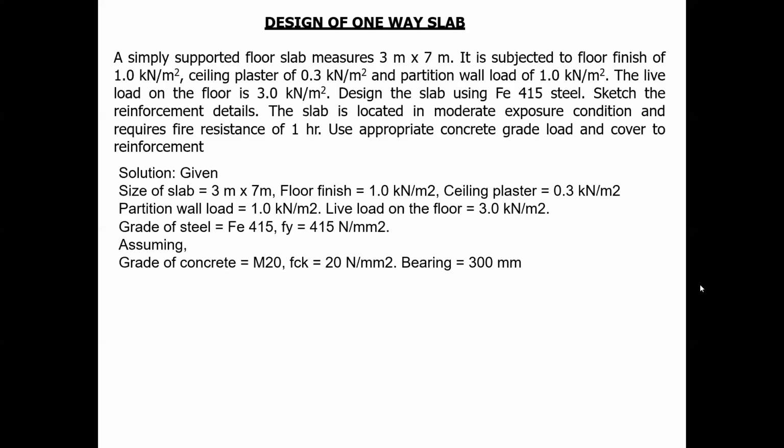7 divided by 3. Good. So take down. Ly by Lx is equal to 7 by 3, which is equal to 2.33, right? Which is greater than 2. Okay. Therefore, the slab is designed as one-way slab.